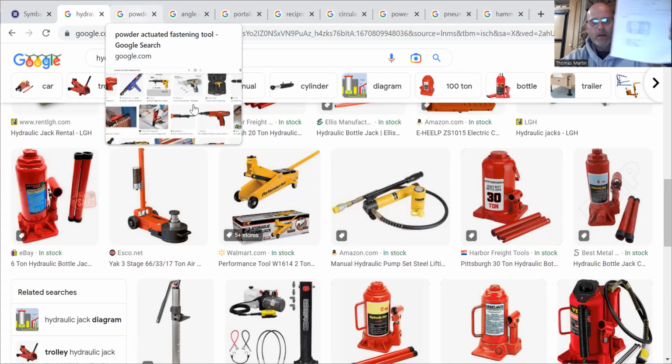But anyway, look on your plot drawings. As you notice, I put 1, 3, 6, 7, 8. I didn't need the rest, I just needed these. That's all I wanted. So number 1 is the double top plate. Number 2 is the header. Number 3 is a king stud, or I'm sorry, number 3 is the header. Number 6 is a king stud. Number 7 is a trimmer stud, and number 8 is a rough sill plate.